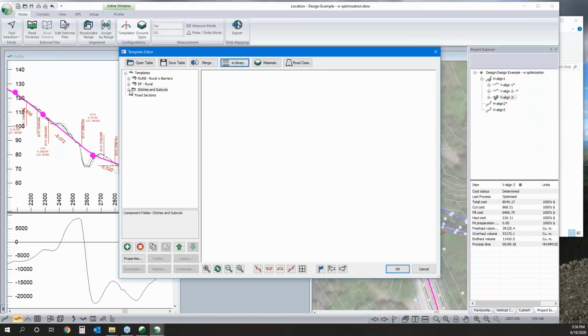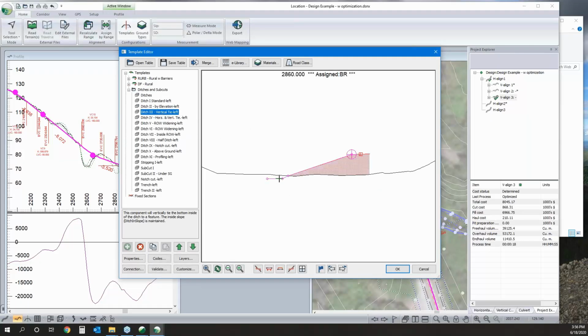So I'm just going to pull this in. I won't do it, but I'll explain roughly what it is. Here I've got a vertical tie, so I can attach that ditch alignment to another alignment, and further reduce my subgrade costs by treating this ditch as a variable alignment that can be used to address my subgrade requirements in the roadway. It's kind of having an optimization loop in there and using one to make the other cheaper. That's an entirely separate webinar.